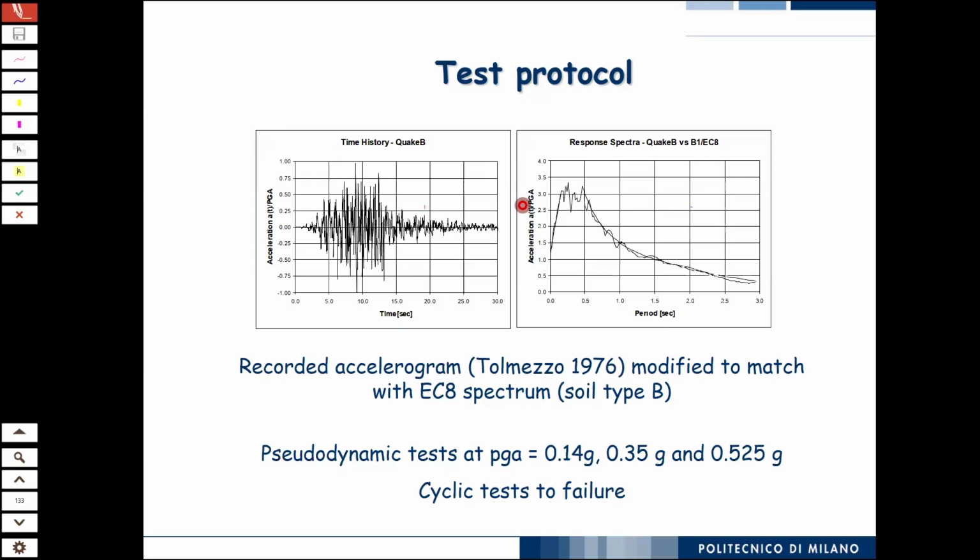It means that you perform a very huge test, and then your test is just 10 seconds. And this is what happens if you use shaking table tests. It takes months to build up the model and so on, and then that's over. And then it's other months to elaborate all the data because you put the sensors and so on. What does the pseudodynamic test do?